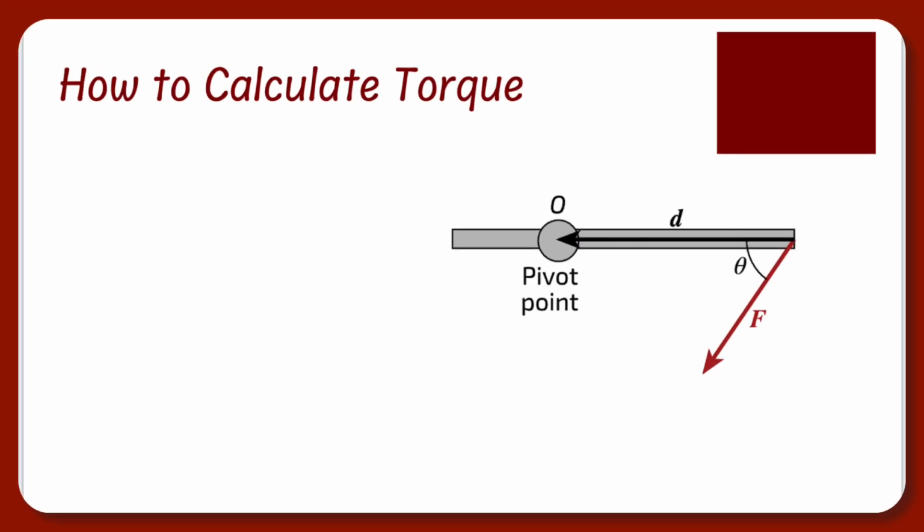So how am I going to calculate torque? To be honest, in my class, I usually say ignore the sine theta because it all depends on where theta is measured from. What I usually say is that you need to have your force and your radius perpendicular to each other. And if they're not perpendicular, like I have in this diagram, then you need to take a component.